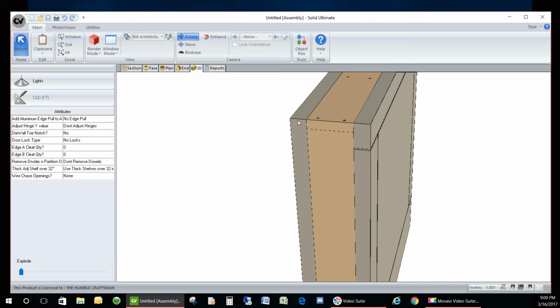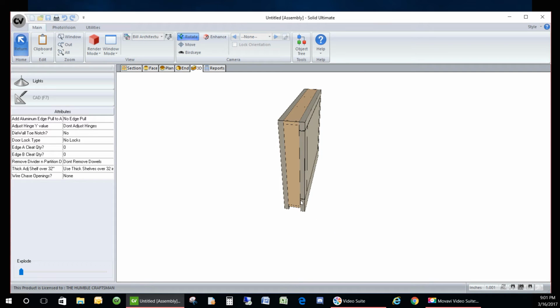And so that's why these are 1.25 inches. So I have my plate at 3.5, then I have 1/2 inch for my cleats, and then 3/4 for my finished skin. Then again 1/2 inch and 3/4. So that gives me 2.5 plus my 3.5. So we end up with a 6-inch wall overall.